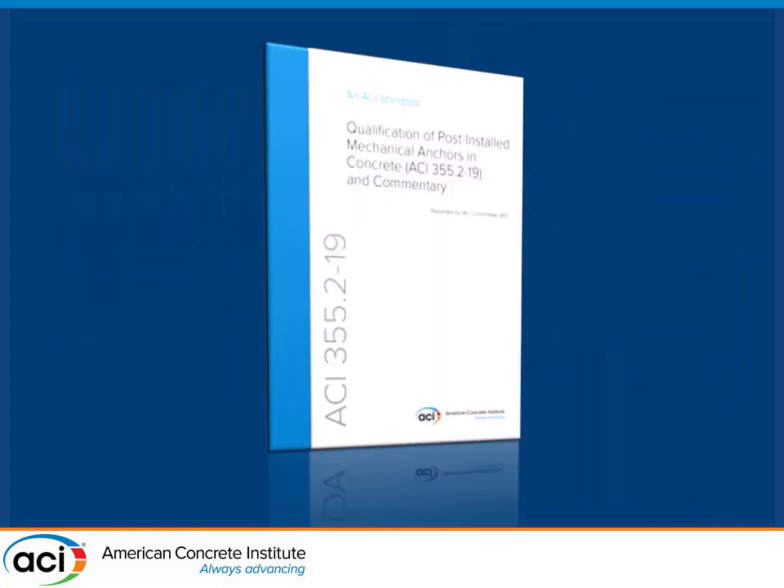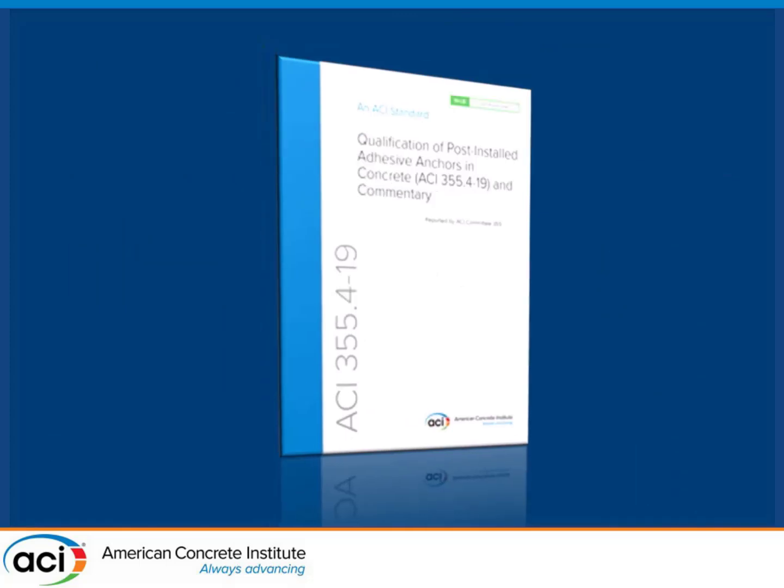You'll find constantly two other documents, 355.2 and 355.4. Those are not intended for you, okay? Don't go buy them. They are intended for the manufacturers of post-installed anchors. These are the rules for them to get their anchors qualified. Now, if you want to become an anchorage expert and understand a deeper dive into what those manufacturers are doing or what they need to test to, the theory or the actual test, this is where you go.